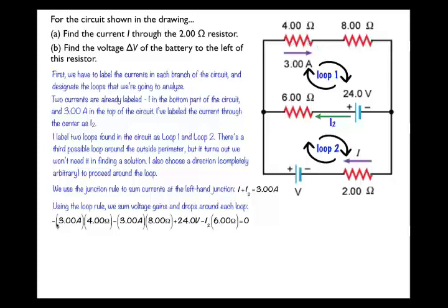It is also negative because the electric potential would drop if you move through this resistor in the direction that the current is flowing. Next thing you would encounter would be this 8 ohm resistor, same idea. 3 amps of current through the 8 ohm resistor would be a drop of minus 3 amps times 8 ohms. Going around the loop, nothing on this side. Get here, I have to take a left at this junction. 24 volt battery here.